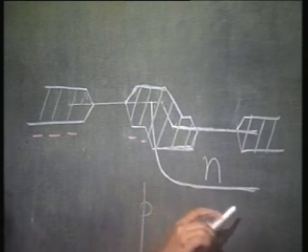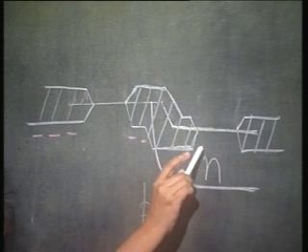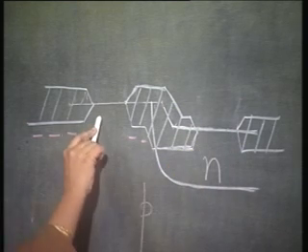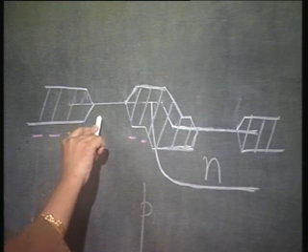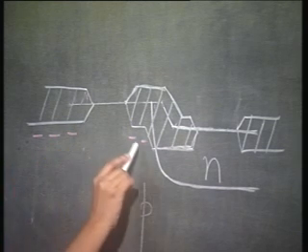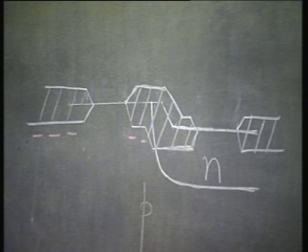You have your Nwell. This is the region where your PMOS is going to be placed. This is the region where your NMOS is going to be placed. You have done the channel stop implantation to stop the parasitic MOSFET from getting inadvertently turned on. Next, you can just follow it up with gate oxidation, gate polysilicon deposition, patterning and source and drain diffusion.